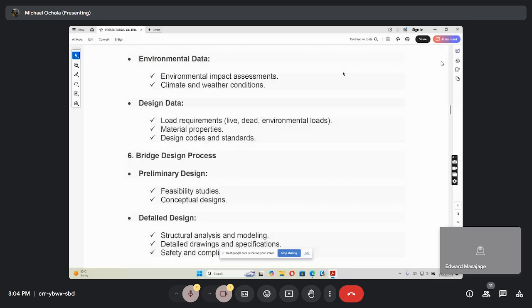That is now the dead load. It is the part, the structure built without any additions. Now, when you begin putting in services, rails, walkways, guardrails, any lighting, lighting poles, we call them superimposed dead loads. They are dead loads, but they come at a certain stage and then they remain permanent.